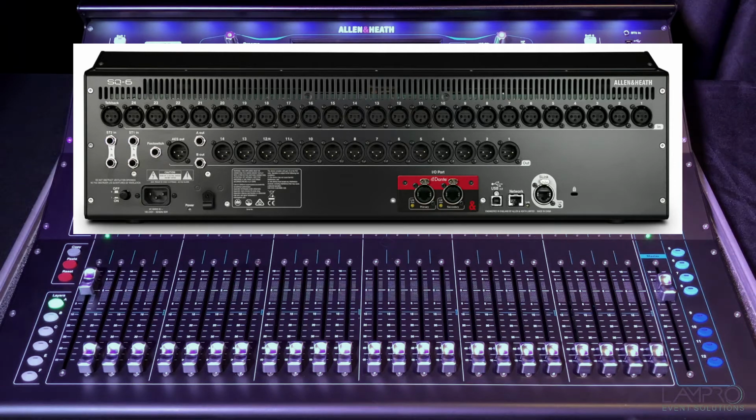The back panel also features 2 stereo inputs on the left that can be used for playback devices, for example laptops and media players. The AES output can be used to send a digital audio signal to a relevant AES device. The alternative A and B outputs can be used as an additional output that can be linked to any of the mix outputs. The I/O port, which features a Dante expansion card at the moment, can be used with a range of different expansion cards, including the SQ Dante, Waves, and S-Link cards.